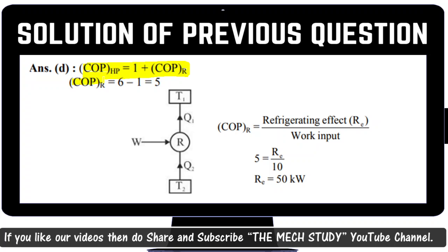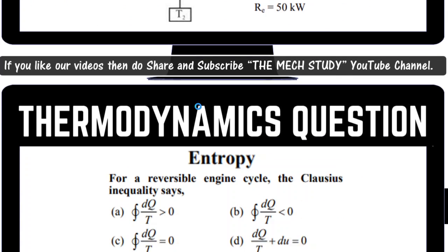The COP of the refrigerator is not given, so you need to calculate it. COP of heat pump is given as 6, and if you subtract 1, you will get the COP of refrigerator as 5. Then you need to calculate the refrigerating effect. COP of refrigerator is equal to refrigerating effect divided by work input. As you already calculated the COP of the refrigerator, you just put it in, and work input is already given as 10. Then you will get the final answer: the refrigerating effect of that refrigerator is 50 kilowatt for the given input. So these are also important questions related to COP.